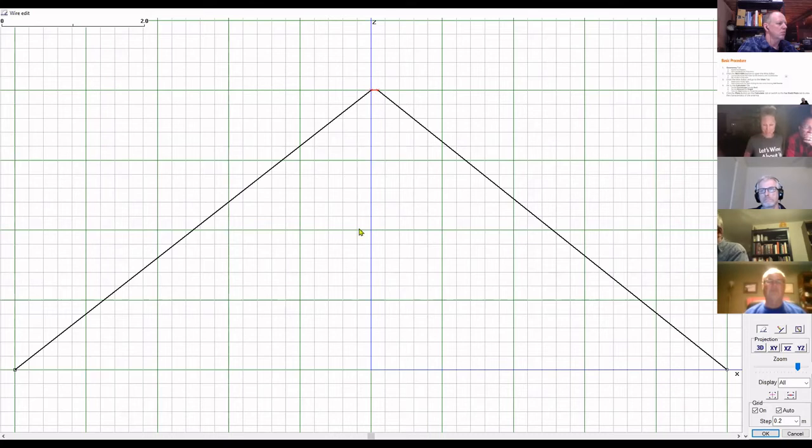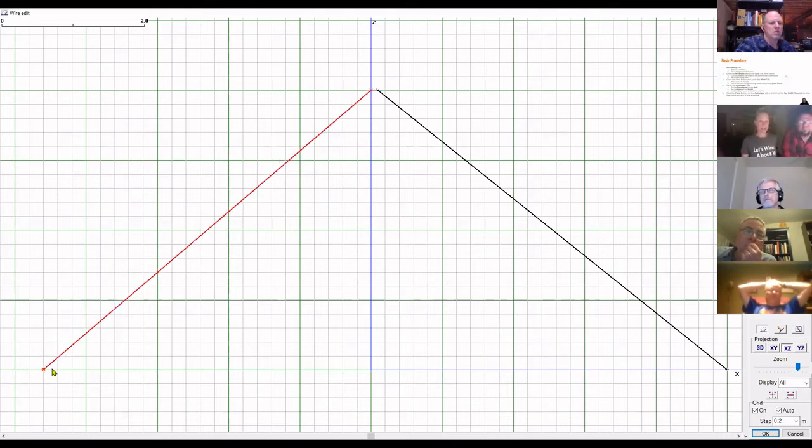Now, a couple things are going on here. One, our middle isn't in the middle anymore. We got to fix that. The second thing is, as we move this up, we're making these two elements of our antenna longer, right? They should have been around 5 meters each before, but now they're more like 6 meters. So we kind of need to pull them in a little bit.